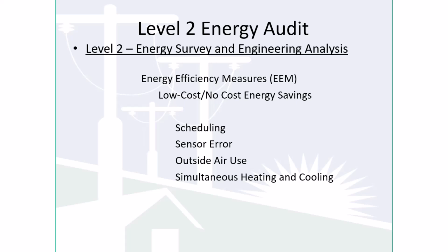Next is the use of outside air. Buildings, commercial buildings, use outside air for typically 2 purposes. The first one is for ventilation. And in ventilation, what the outside air is doing, its intent is to displace indoor polluted air. For instance, off-gassing from carpets or respiration from people. That is an indoor air pollutant, and the outdoor air is used to displace that, get it out through the exhaust system. The other use of outside air is for free cooling.